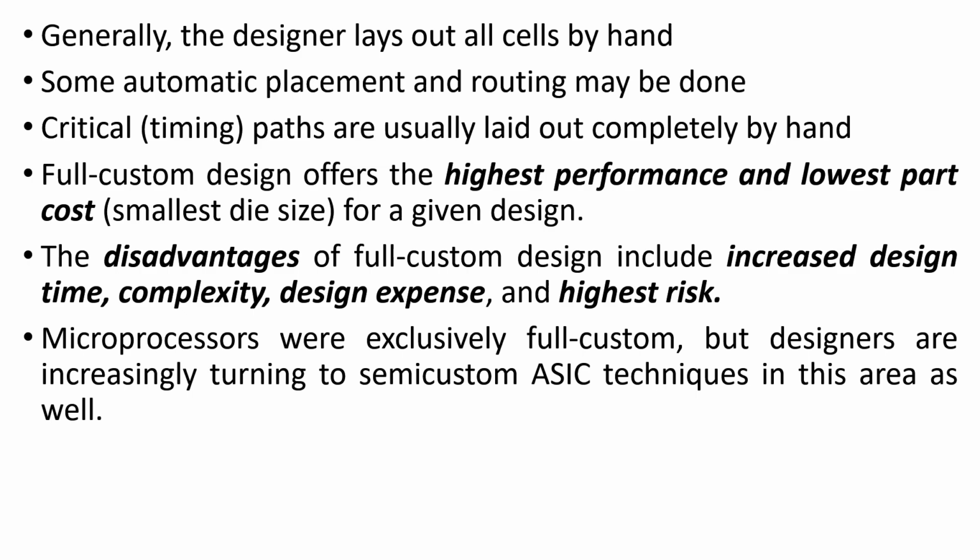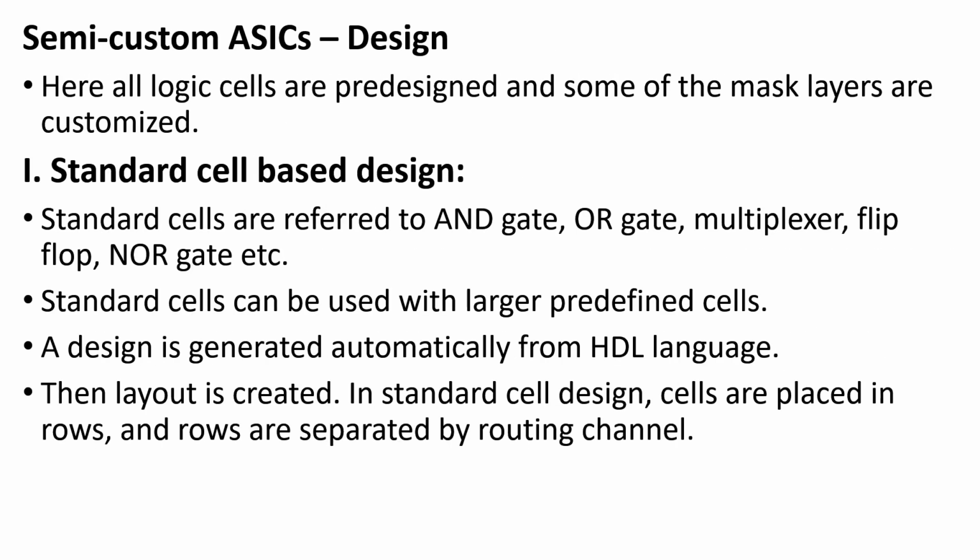When microprocessors are implemented using this full custom design, nowadays the designers are also turning to develop semi-custom ASIC techniques in this area. Semi-custom ASIC. Here all logic cells are pre-designed and some of the mask layers are customized.